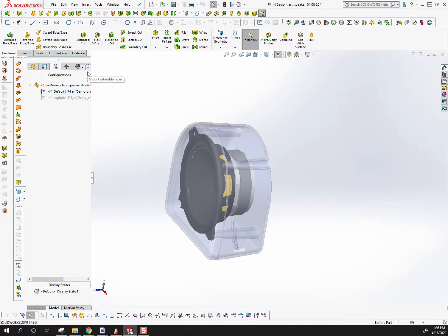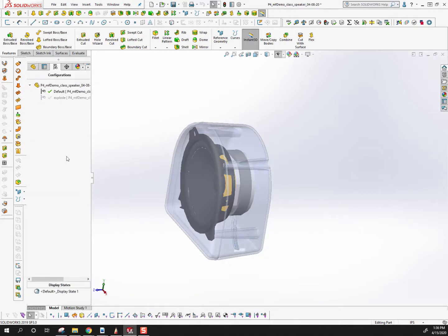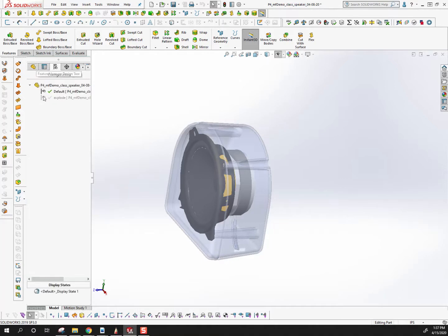That's the automatic way to do it. That's how SOLIDWORKS remembers it: creating a new configuration, adding a couple more commands, and then going back to your default will undo the commands you just did. And by undo, really, it's just turning them off. They're still here. Another way to think about it is that configurations just remember whatever is suppressed or unsuppressed.